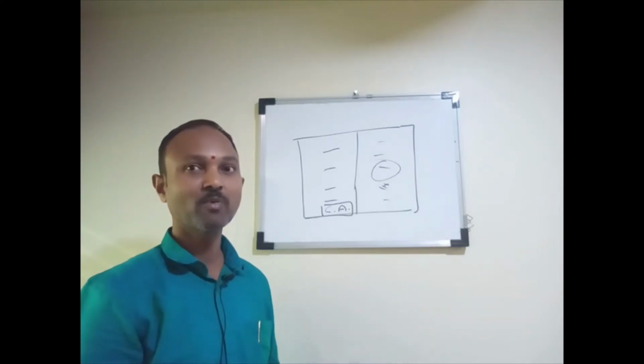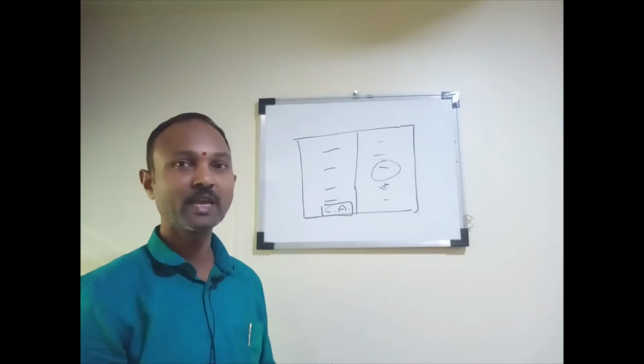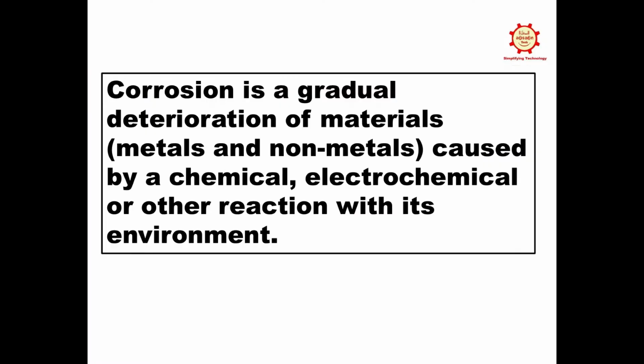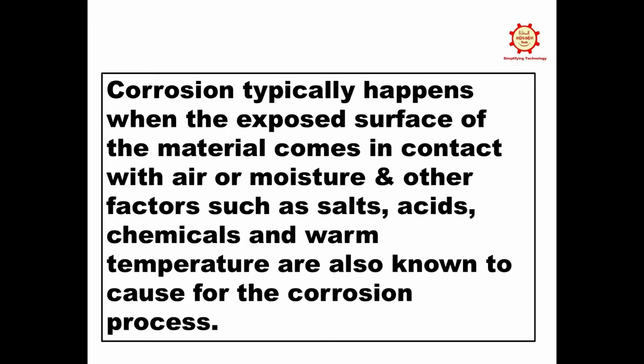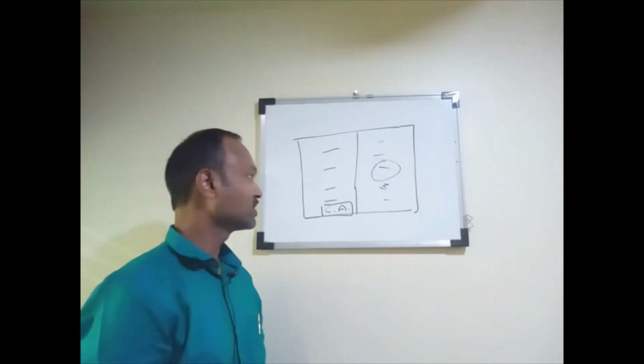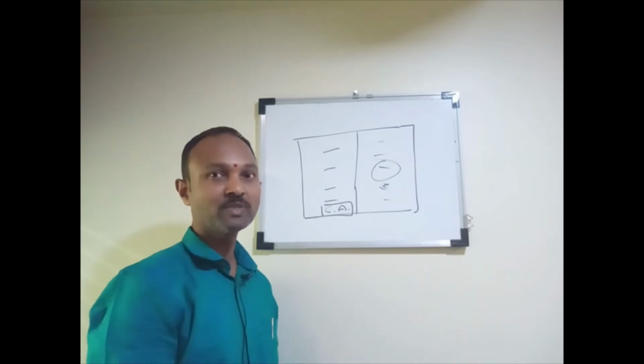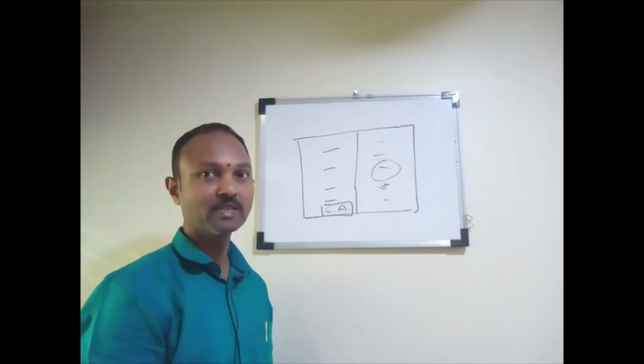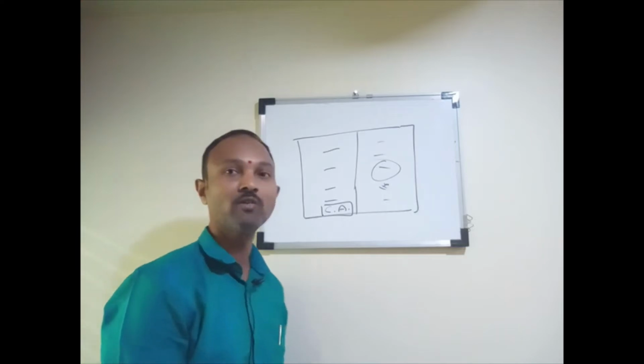This is a similar type of decay of that material. So for the vessel to last a long time, we need to add some corrosion allowance.